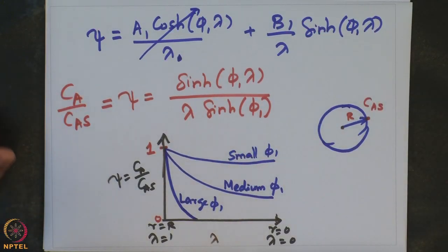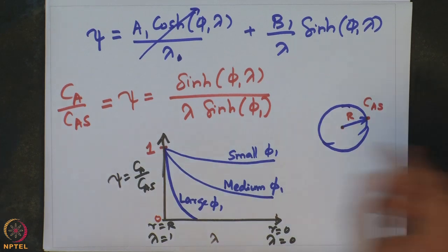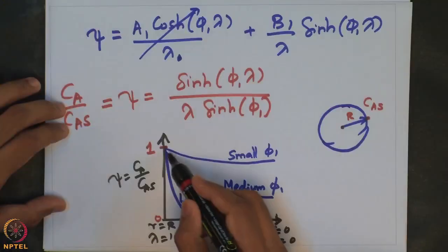On the other hand, what happens when the Thiele modulus is small? Then the diffusion rate is sufficiently higher compared to the surface reaction. Therefore, sufficient quantity of the species is always present everywhere inside the catalyst. It diffuses fast enough before the reaction happens, and it is the reaction which controls the overall reaction rate. That is nicely captured by this picture here.